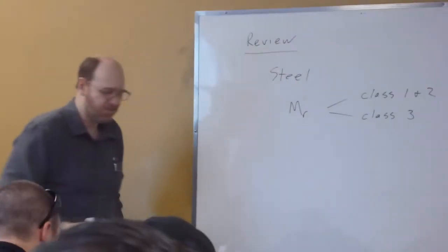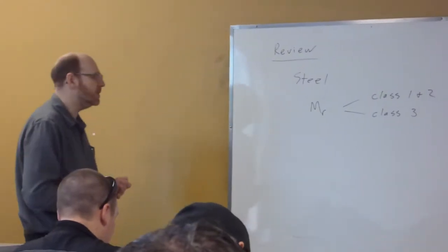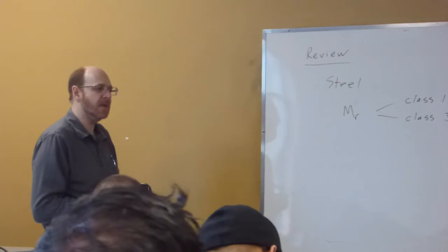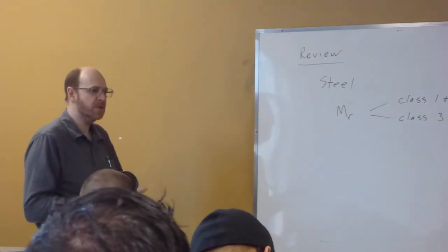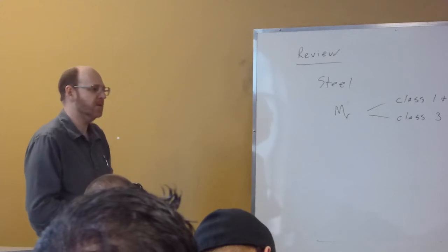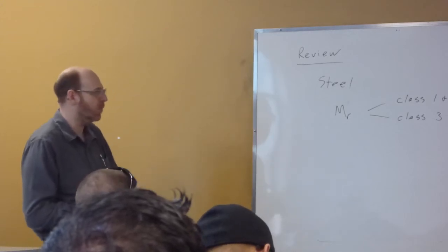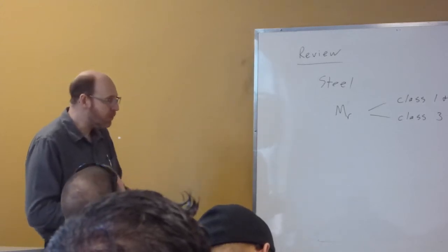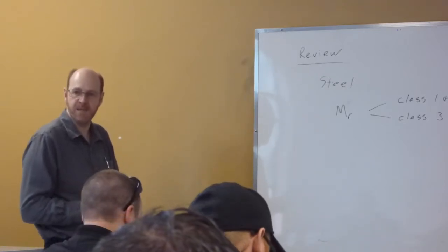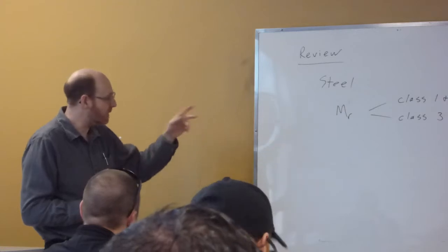And there is a class 4, which we briefly alluded to, which is mostly based off of the S136, which is the light gauge steel construction. Of course, our steel code that we're using is S16, so there's a different code involved for light gauge steel construction, which is the class 4. The big difference between these two is whether you use elastic design principles or plastic design principles.